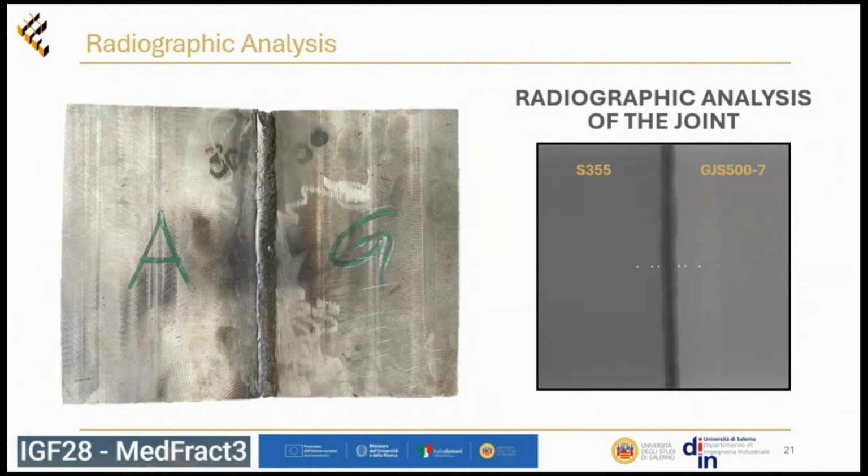After the welding process, we wanted to evaluate the quality of our welded joint. To do this, we performed a radiographic analysis. We can say in this radiography, no particular defects are present. We can appreciate the 6 holes for the thermocouples, and the different color of the welding bead and the 2 plates, depending on the difference of density of steel and cast iron.